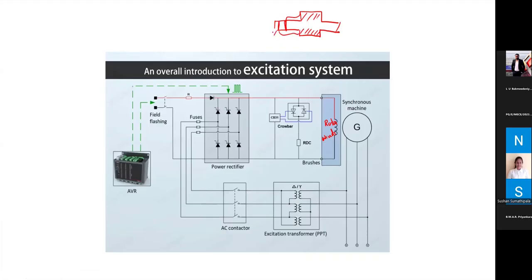So these are slip rings. They are individually isolated metal rings connected on the shaft, and to provide DC power, we have brushes like the normal DC motors that you have learned in your ordinary level classes. You have these brushes touching them, which we provide with the DC current voltage source.